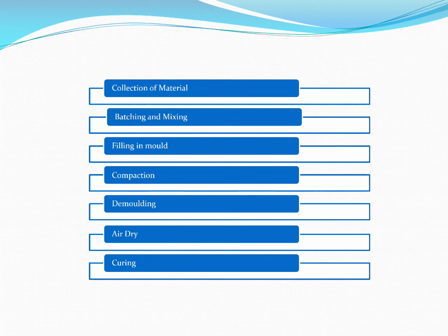This is our methodology of construction. Number one, collection of material. After that, batching and mixing of material. Then filling in the mold. After that, compaction, demolding, air drying, and lastly curing.